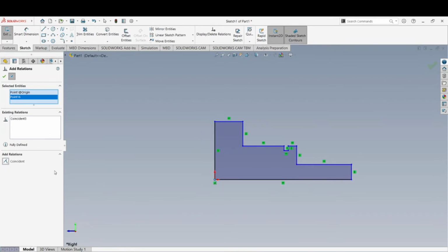And when I do that, since I locked that point to the SolidWorks origin that is not movable or fixed, that makes these two lines black because they are now fixed. They cannot be moved. Like this one can't be moved up or down. This one can't be moved in or out. So I'm going to say OK with my mouse, left click.